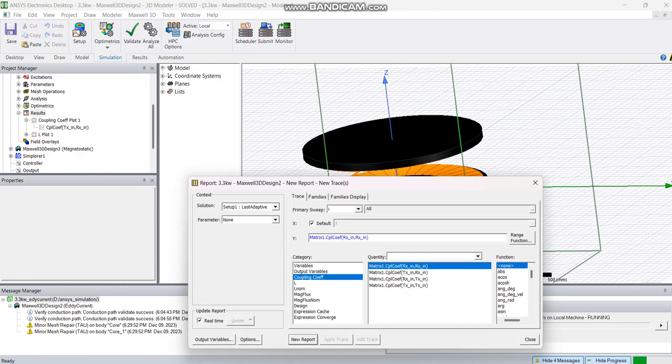In this data table, you are going to choose matrix from parameters. If you want your sweep to be the dx, the changes in the z direction, you click this dx. If you're interested in the primary sweep based on the current, you click that.